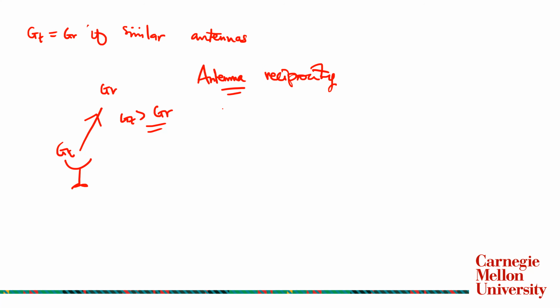But in general terms, like in the case of satellites, we might design an antenna for the Earth station because we want it to be bulky for purposes of transmitting a lot of power. But for the satellite, we are limited by the size, so we have to design a small antenna. Otherwise, in most systems, an antenna has the reciprocity principle, which essentially means that it can work as a transmitting antenna as well as a receiving antenna.